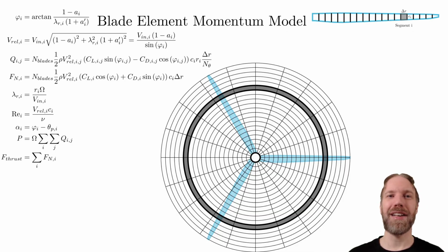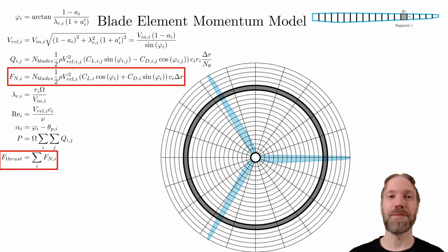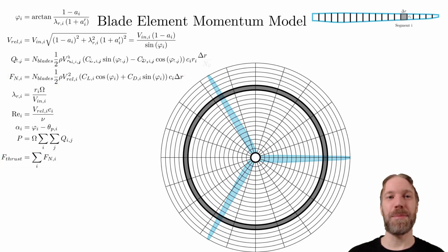Considering that we are most likely to do it in a computer, this method is so fast that one should not worry about the computational time though. The same modifications can be made for the normal force and the thrust force. To make the text in this video a bit cleaner, I will drop the double indices here though, and neglect this azimuthal variation.